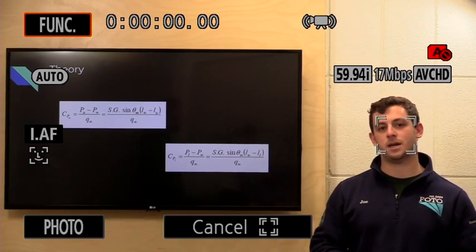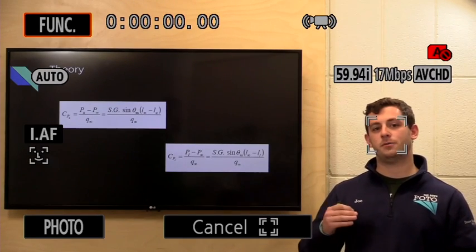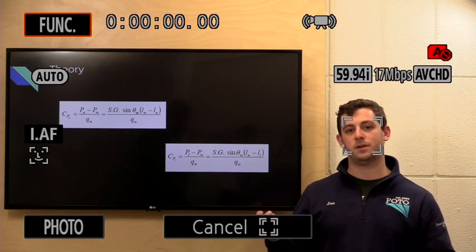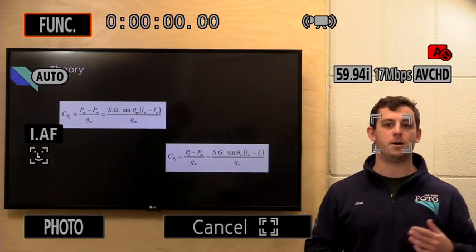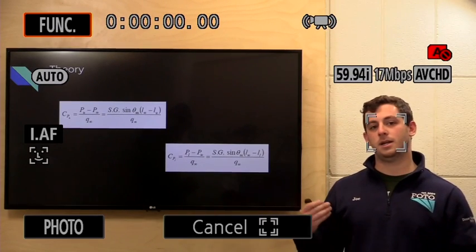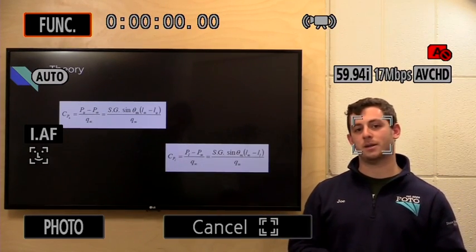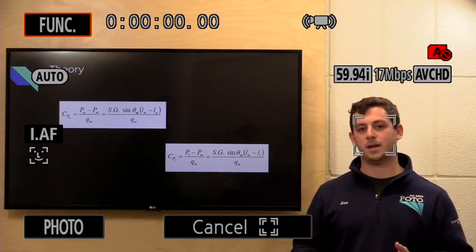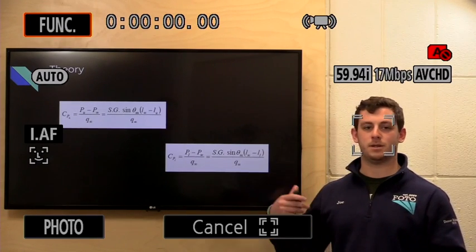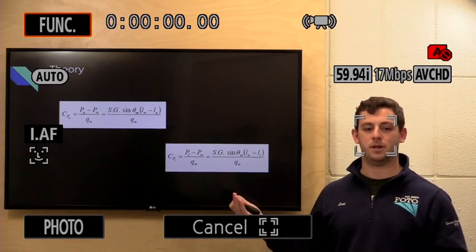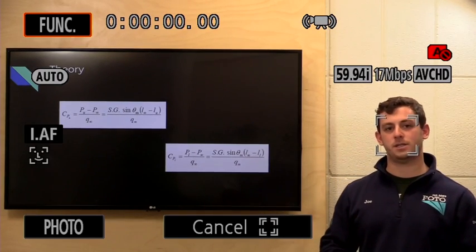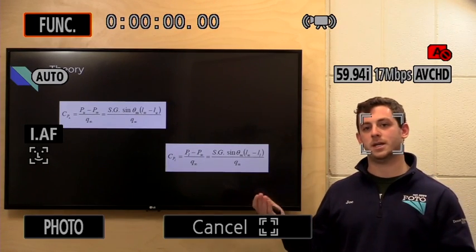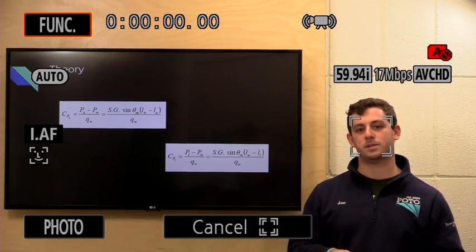And as you can see, into the calculation, we have to look at things from our actual experiment. So SG here represents specific gravity, which in the case of our experiment would have been alcohol in our manometer tubes. And sine theta m represents the bank angle of our manometer device, so that whatever bank angle we use for the manometer is taken into account in our final calculations and is still concurrent with our theory. We then have our readings here where we're comparing free stream velocity, free stream pressures versus the actual pressure experienced on these individual points on the airfoil.